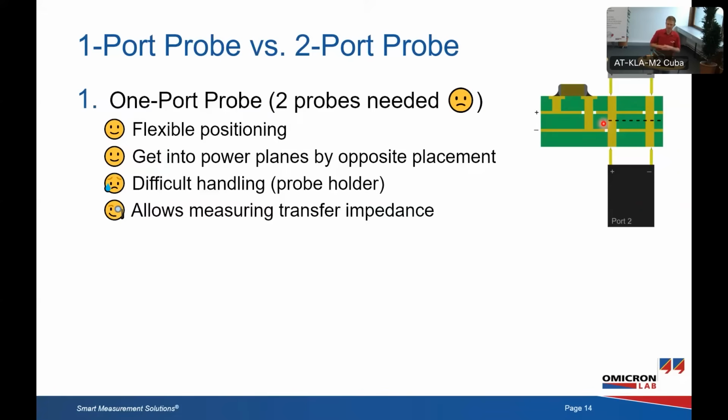The disadvantage is, besides that you need 2 probes, that handling is more difficult. I'm not able to position 2 1-port probes at the same time and hold the PCB and then start the measurement. I'm missing at least 1 arm for that. So you need a probe holder or something like that. That's a little bit more effort.